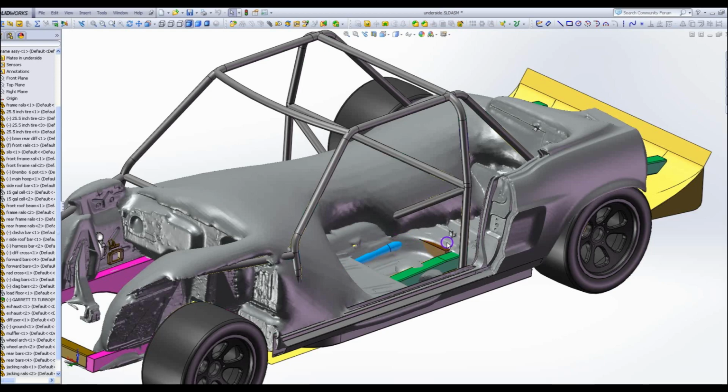So I'm using this STL file that I scanned as my template. I can move it back a half inch, quarter inch, whatever. It's accurate enough for that. And then I got to leave a little clearance. And the way you do that is by just moving this guy in the frame assembly. You keep moving it back a half an inch until you can't see it anymore, right?